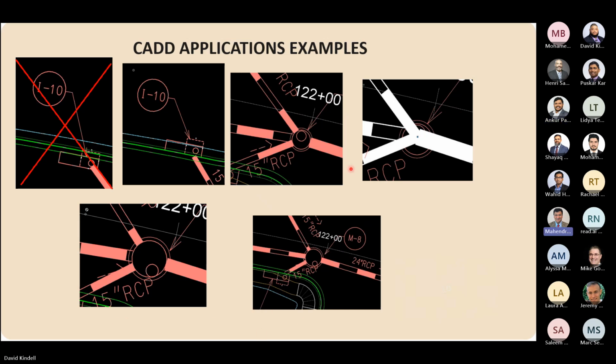Yep. And another thing I'd like to add: if we cannot fit the pipes within the range of manhole diameters we have, then the next option, for the project to be constructed anyway, is to have a special structure, a vault. That is where structure people need to be involved. That is another story.